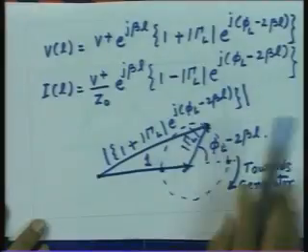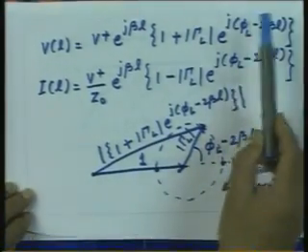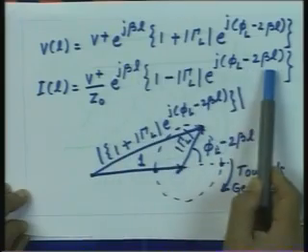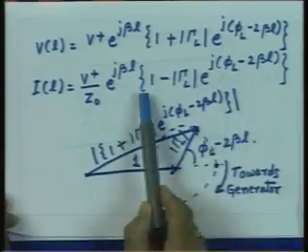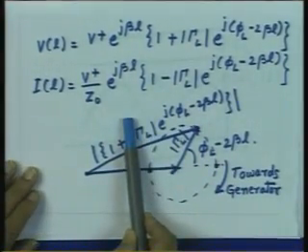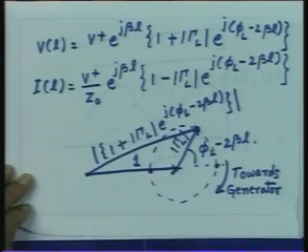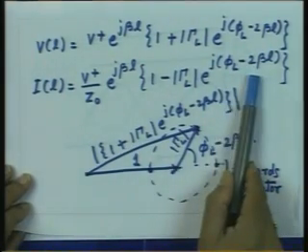As we have seen, the phase of the signal in time gets translated into the space phase, because the total phase we see on a wave is a combination of space and time. In other words, the phase relationship between the two waves, the forward and the backward travelling wave, is related to the time phase as well as the space phase. And since this total phase governs the location of the maxima and minima of the standing wave, by noting the location of the maximum and minimum on the transmission line, one can estimate the phase of the signal.